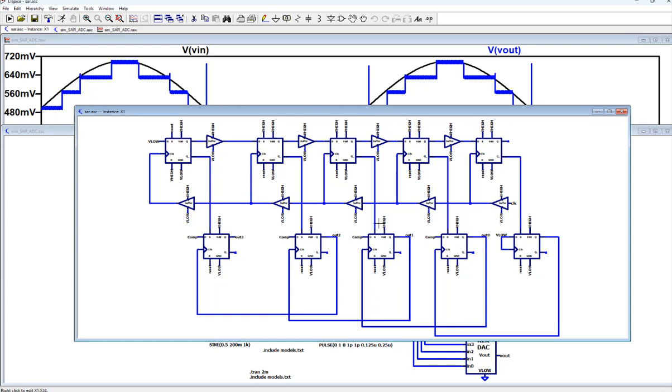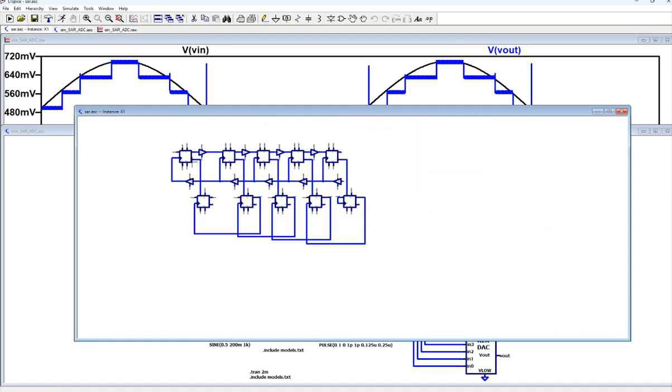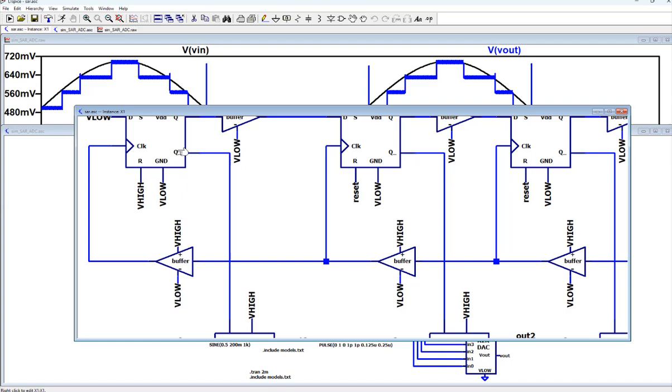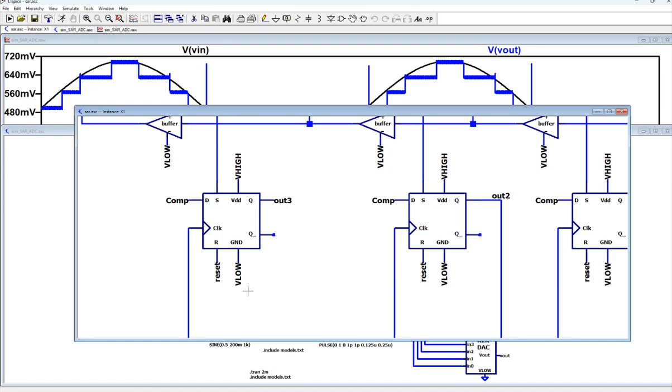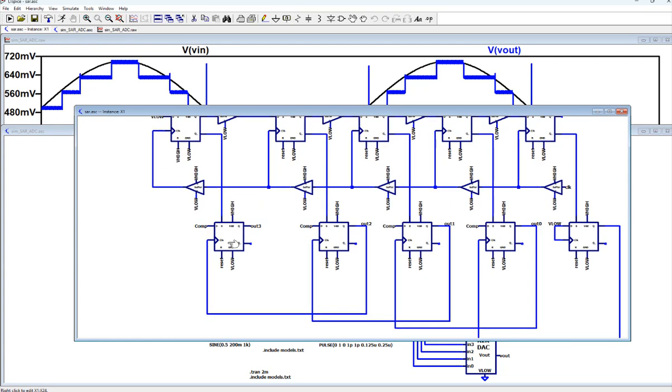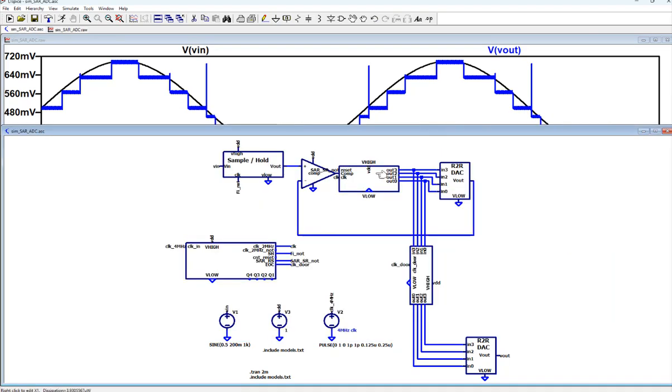And that's the sequencer, the code register, like the circuit I showed you on the paper from the notes last time. It's the same circuit. You can see I'm using Q0, right? Does that make sense? Use Q0. Okay? Because for the ones that I'm not resetting or setting, I just connect them to high, right? Because only 0 triggers it. So this is a SAR block. It's really simple, just D flip-flops. Okay.